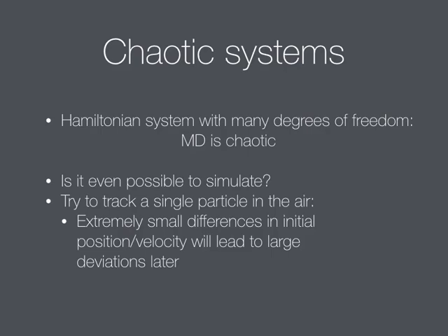And this basically means that if you do 100 steps or so, then you can see differences up to very, very significant digits in some results. So if you want to follow the trajectory of an individual atom, then it's very difficult to get that very accurate in this way. Or at least you could get it accurate, but you have to do a lot of effort. That's not what these codes are usually optimized for. So even if I compile, for instance, the package with different compiler flags or a different compiler, you get different results very quickly after 100 steps or so. You can see significant differences.